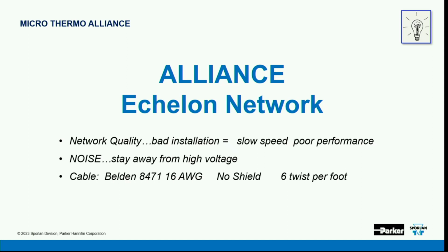So if you're subbing out your work to a low-voltage contractor, he says, dude, I got it. I do networks for 30 years. Make sure he realizes that this is an Echelon network, not BACnet, not 485, because the cable requirements are totally different.